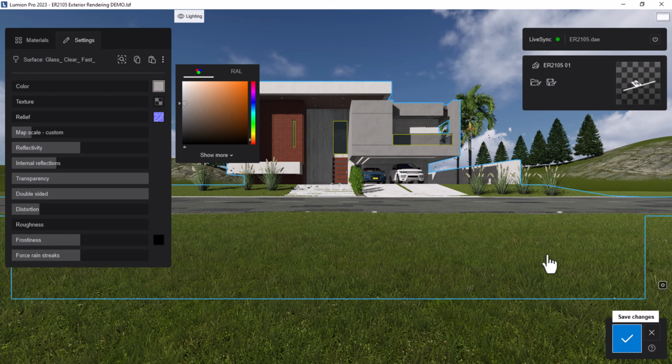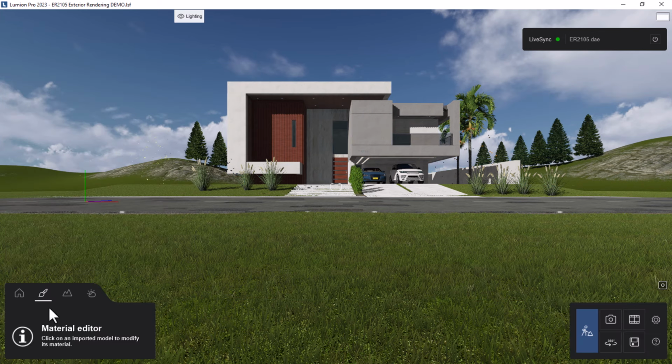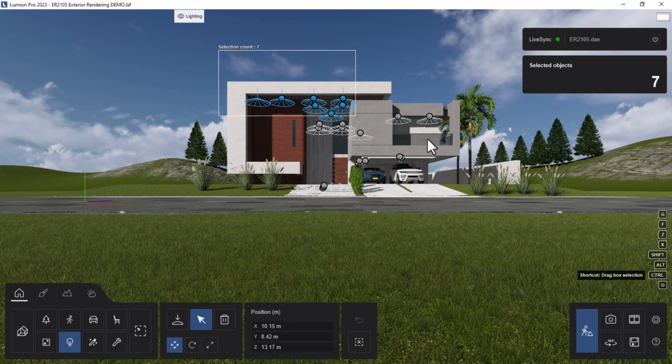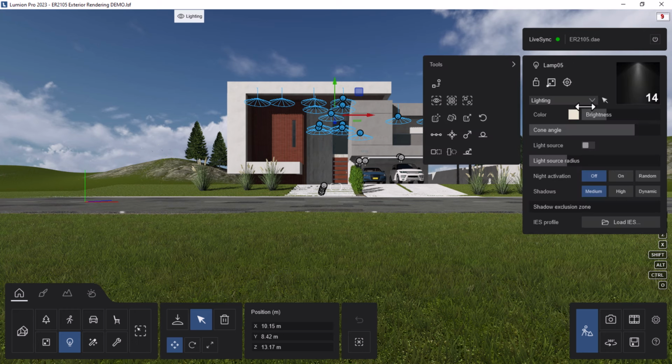Okay, I think one thing that I need to do is to turn on the source light for the slide so that you can really beam in nicely. So I'm going to go to content library, make sure the lights are active, and then I'm going to hold Control on my keyboard, then select all the slides. Then I'm going to show the light source. Okay, maybe I could increase the intensity a bit so that it lightens up that space.